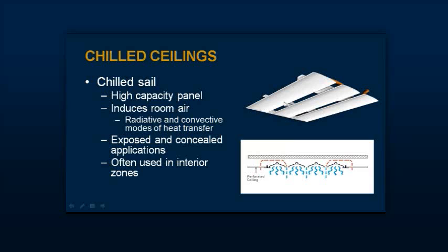So what you get is a higher capacity out of this with very low velocity and a great deal of thermal comfort, because I can handle more of my sensible load with this product with less surface area than I can with, say, a radiant panel. And because of the breaks between the airfoils, I can actually have absorptive material above them and also mitigate sound.